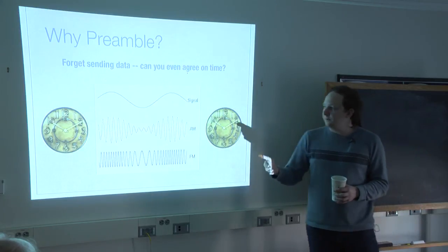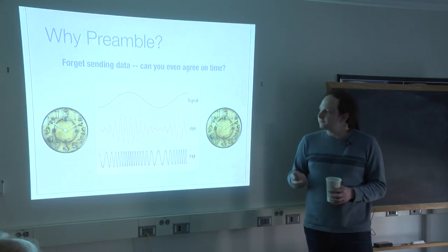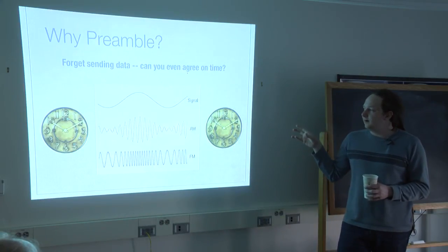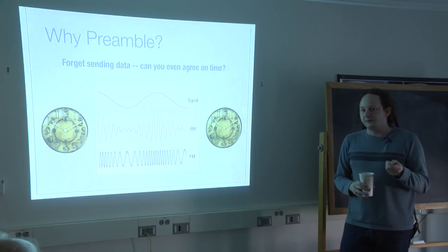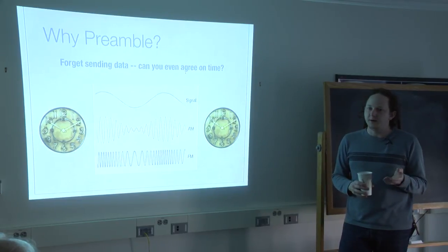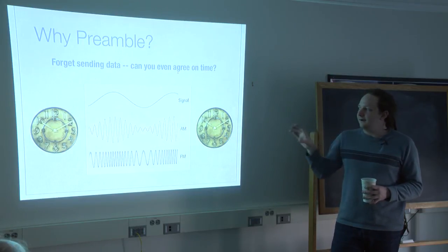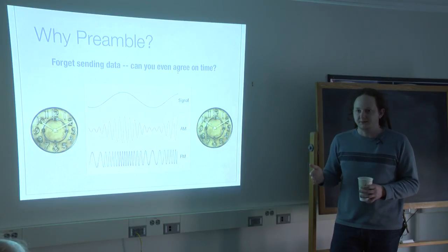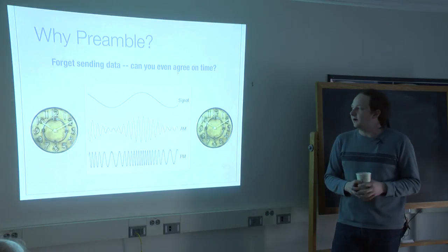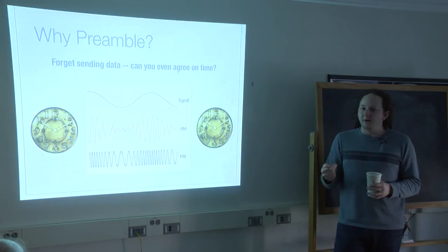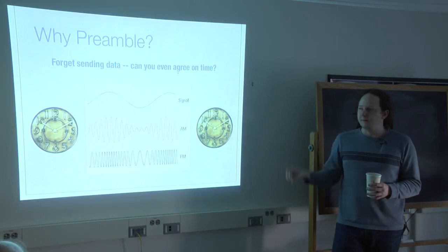The longer the ship would stay at sea, the further its clock would drift from its setting on land. And in today's radio world, you have the same problem. You can get high precision timing signals from an atomic clock or from GPS. But the data is coming across very, very fast. So as these bits and subsymbols called chips are swinging, the receiver has to know at exactly which time to sample the signal to determine what the incoming bit is.